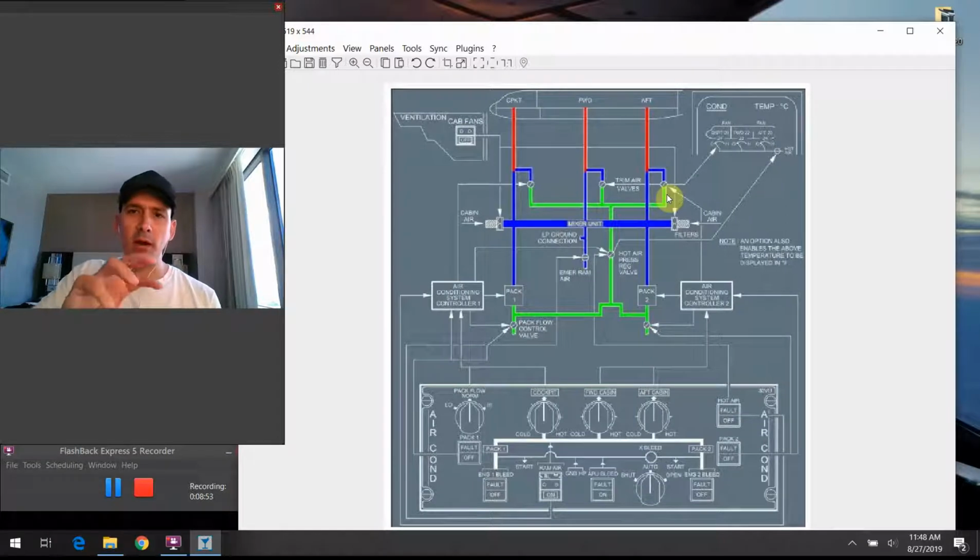And that hot knob could then be twisted to add a little bit more hot water to the system, a little bit more, take a little bit out, and regulate it to get the final temperature that you're actually feeling on your skin if you're holding your hands out or taking a shower, or like we said, running your hand underneath the bath water. So that's the analogy of the way to think about what these hot trim air valves are doing for you.